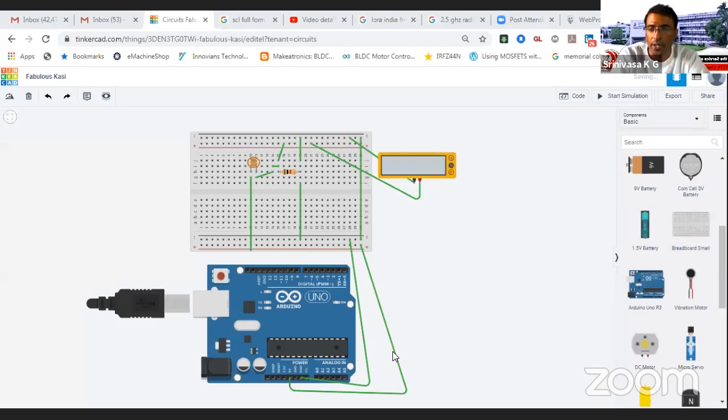Some of the participants were asking in the morning session whether we need to connect an ADC with the Arduino microcontroller. There is an inbuilt ADC in this Arduino microcontroller, which is from the ATmega328P series. So there is no need to connect an extra converter or ADC. How do we use it? First of all, we have to take this output and connect it with the Arduino.